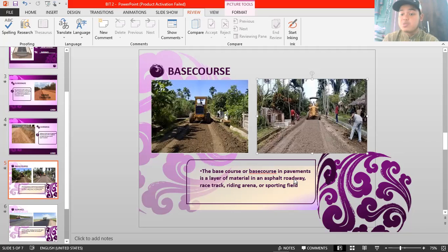After the wearing course, the asphalt surface layer, the axle load is connected directly into the base course. This is why the foundation must be strong. It is the strongest and thickest course in the road structure.